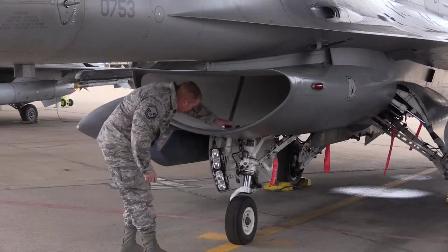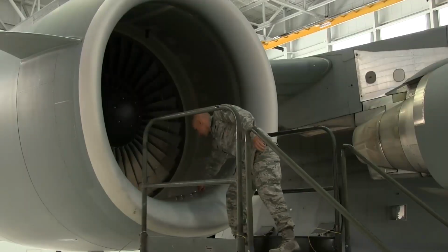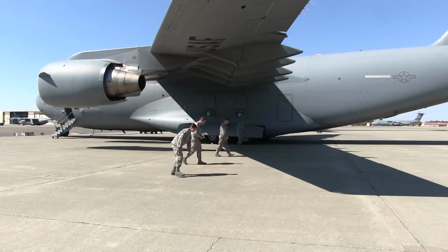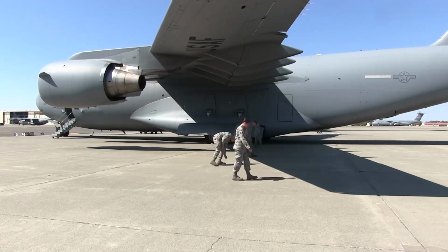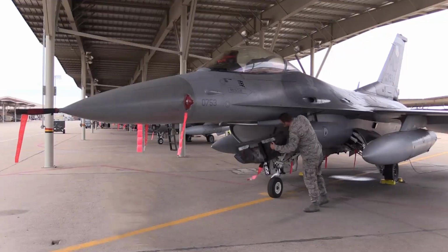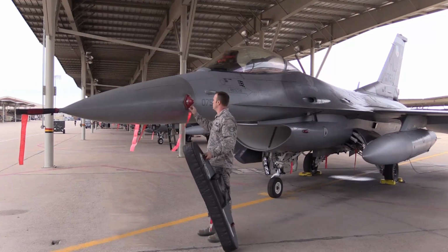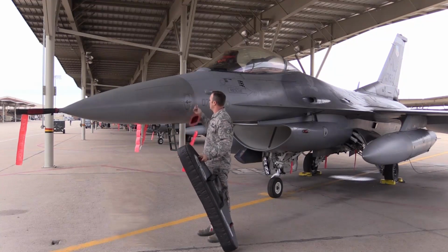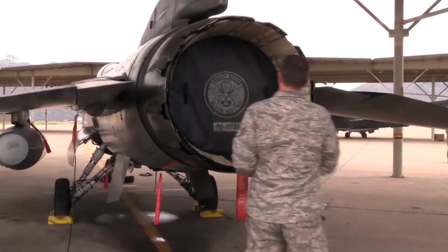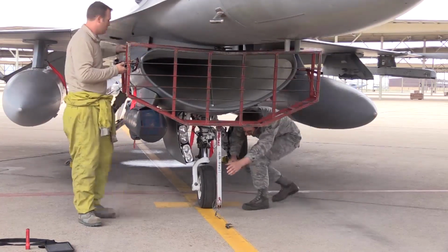Sufficient illuminated light sources must be used during intake and exhaust inspections. Items will not be placed in engine intakes unless relating to inlet maintenance, inspections, or blade blending. Clean up jet blast areas and helicopter pads of debris prior to engine runs or helicopter hovers. All -21 covers will remain installed as close to crew show as possible. Examples: FOD strips in the cockpit, pitot tube, engine, exhaust, and ejection seat covers.